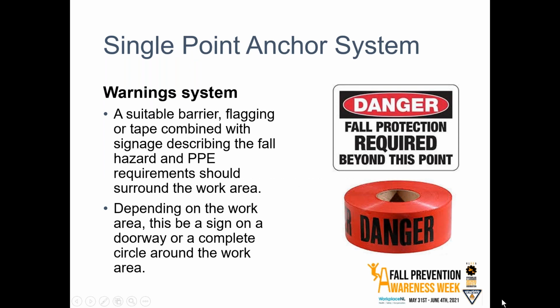With single point systems, it is a good idea to have some kind of system around the area to warn other workers that there's a working at height hazard. And I do think that fall protection and working at height, when you're doing it from the planning perspective, it's really two pieces. It's protecting the workers that are actually doing the work, so the ones that are at risk of falling, but it's also protecting everyone else who might be at that work site from potentially entering into the area where that work is going on. So again, there's the workers that are in theory protected, assuming your system is set up correctly, and then there's those unprotected workers who might just be in the area.